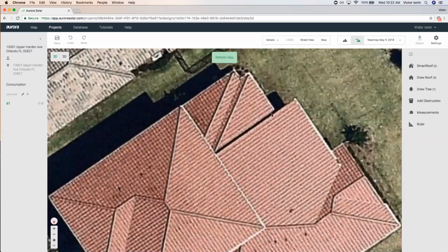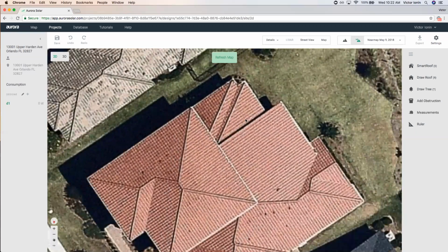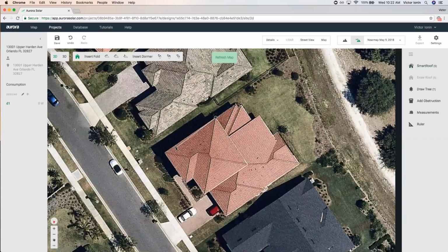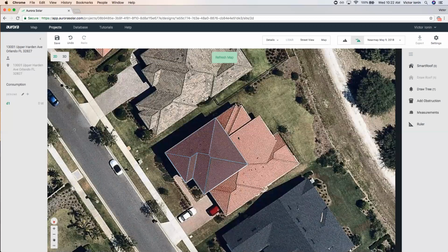And what I also notice is a shadow between this section and this one in the upper corner. So that could also mean a height difference. So maybe I split this drawing into three pieces: upper level, then lower level, and then the lowest level. Smart roof. Let's go ahead and just outline the top piece. Top piece is easy. It's going to line up really well, and it's a hipped roof. So there's nothing I need to do here. So that's the top piece.